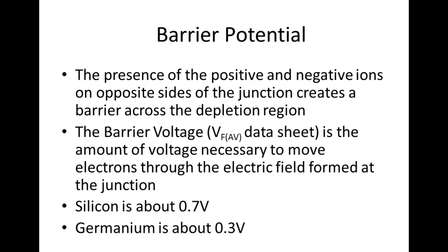This thing will start breaking over around 0.5, and gets up into pretty good conduction around 0.7. Then when you keep conducting and put more current through it, the VF is going to go up a little bit, and with less current it will vary, but it's not going to vary very much.